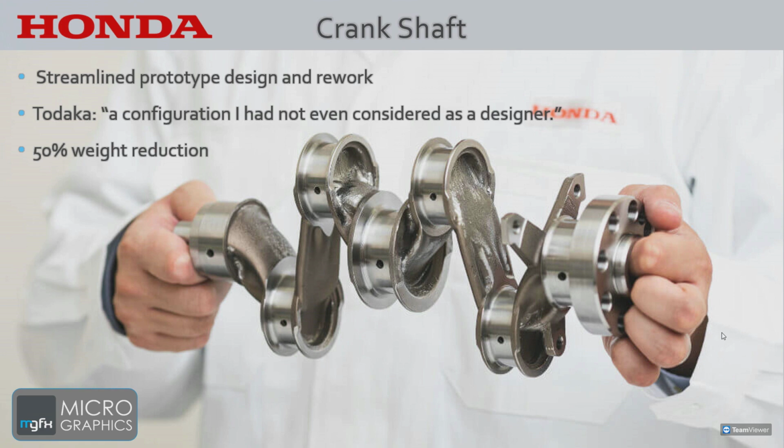And also what I like about this over here is that you can actually see that they've used different manufacturing processes. They've used a combination of additive to build it up, and then to make sure that they clean it up nicely, they use subtractive. So they put it through CNC or mill, and then they turn it to get the nice finishing that you now see on the system. So it works not just with one system, but with many different types.